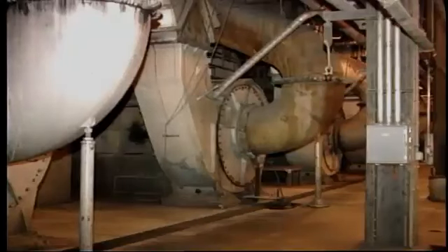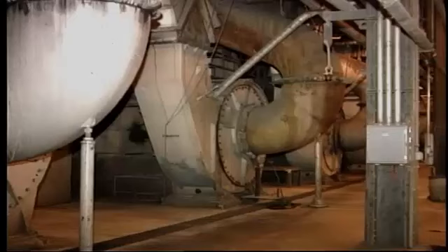In this arrangement, the exhauster fan is conveying both primary air and fine coal dust on its way to supply the burners. The result is a great deal of erosion and wear on the fan internals, requiring regular downtime for maintenance. Now, how do we control the heat input, that is, the fuel input to the boiler, from the burners?